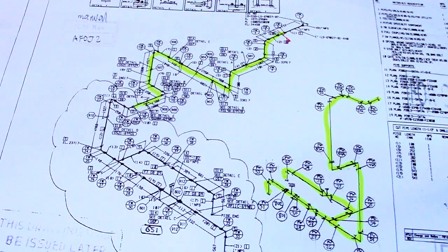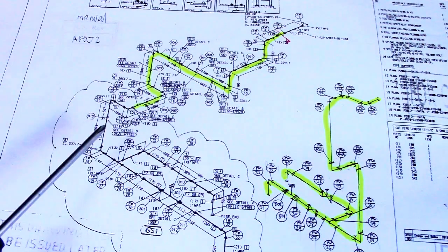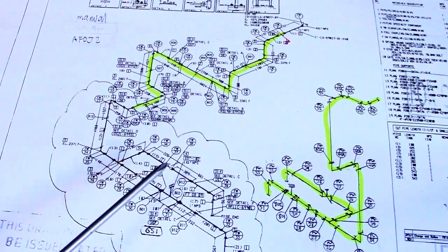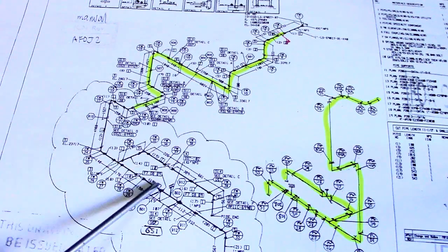Okay, something like that. So this is an example of an as-built drawing. During line checking, if you are line checking in the site, and you see there are some additional joints that are not in the isometric drawing, just put the remarks here in the isometric drawing.